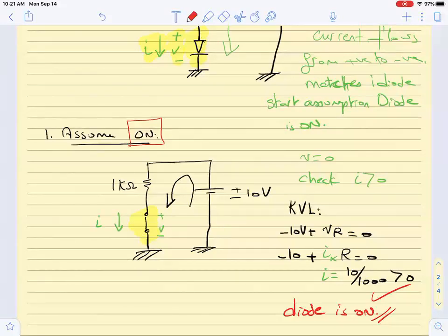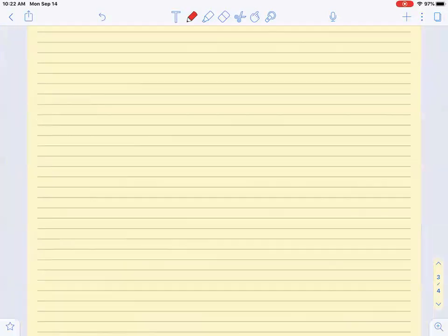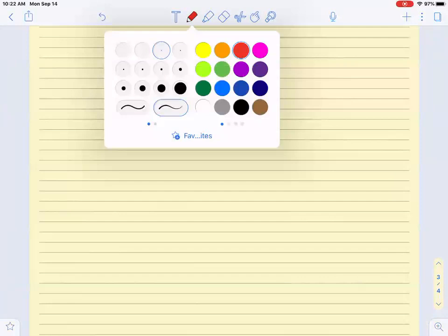to know, if the diode were not there, before we solve, even if we remove it, cover it and put a short circuit, how do I expect the current to flow? For example, I will give you a simple example on the second page. Sorry, I will make it a bit more complex and then we come back to the simple example of the off case, and we will see how it works if my assumption is wrong. So let me assume that I have a voltage here which is plus 10, right?